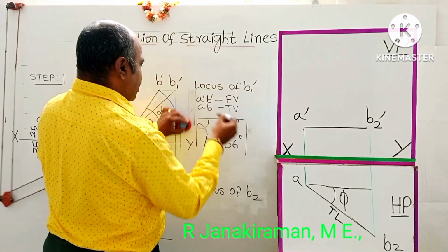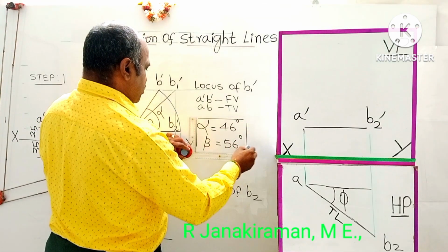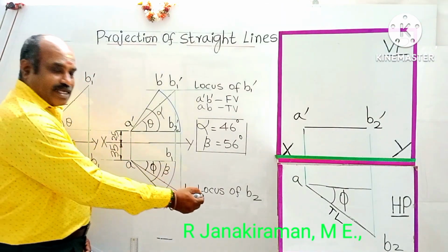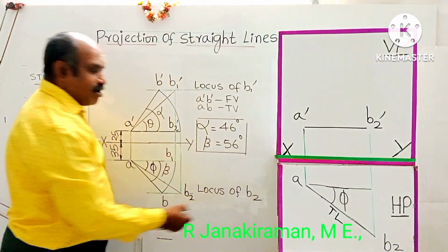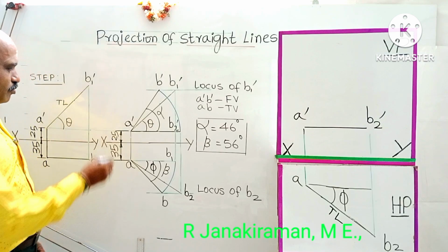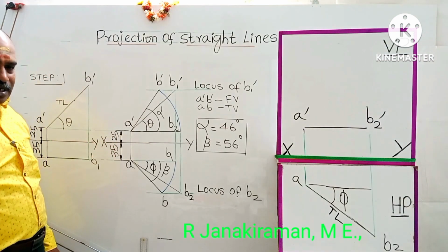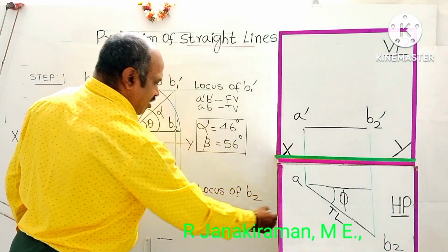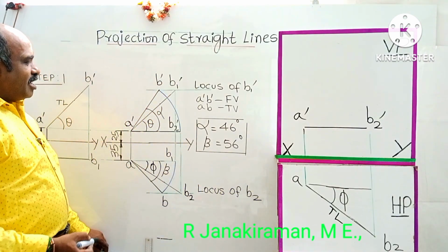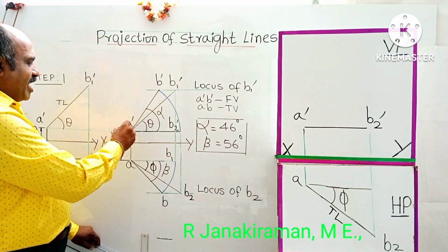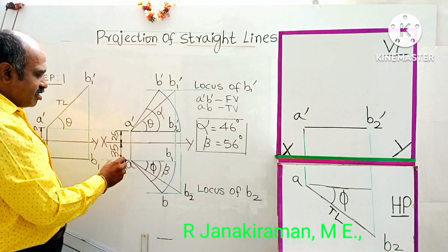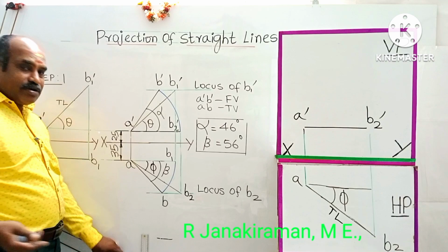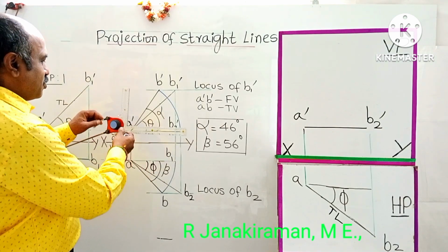In the right side lower part of your answer diagram, you can draw two guidelines and write that all dimensions are in millimeters. This 25, 35, and all are in millimeters; mm is the unit. All dimensions are in mm. Further, this true length A dash B1 dash or AB2 will have the same length. Any one you have to dimension is given as 60 mm in the question.